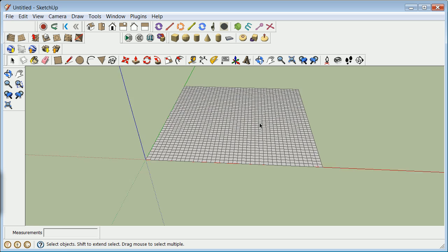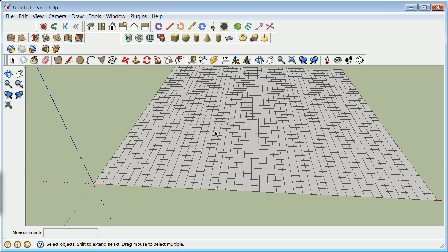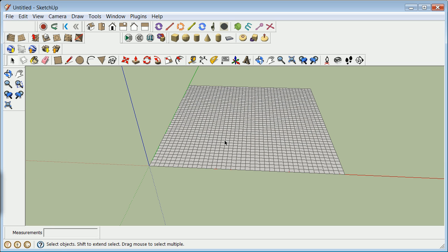All right, now I'm going to show you the smooth tool. So this would be the information that's gridded out that you would generally get from something like Google Earth. So the smooth tool looks like this. You've got the tools in the sandbox, which is to create tin from contours from scratch. That's the smooth tool. That's the stamp tool. That's the drape tool. And this is detail or flip edges.